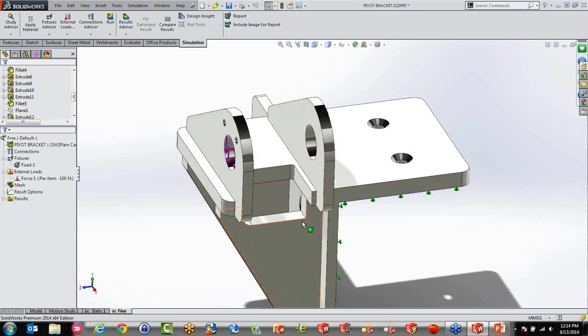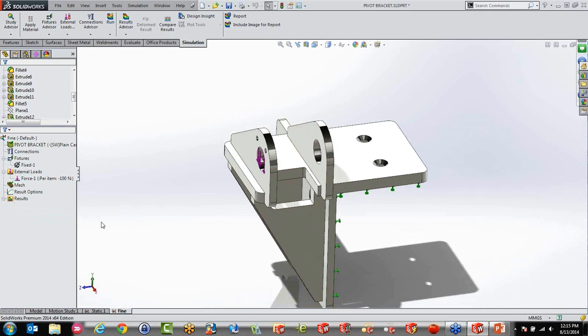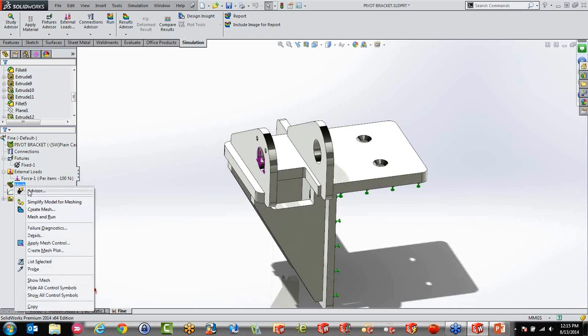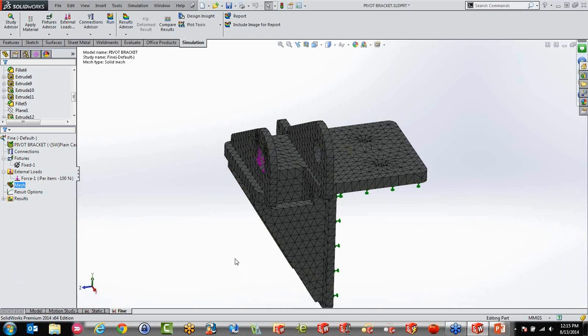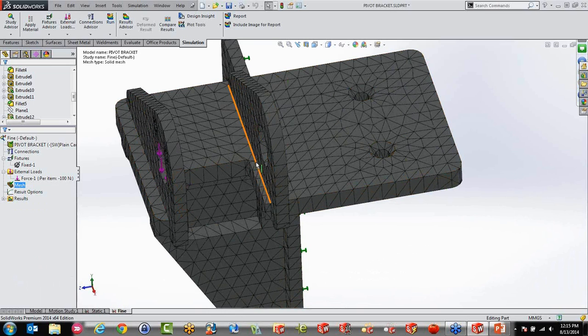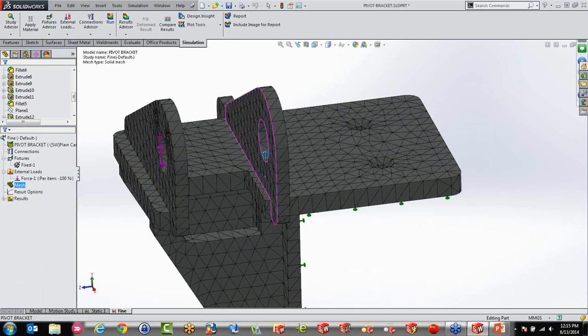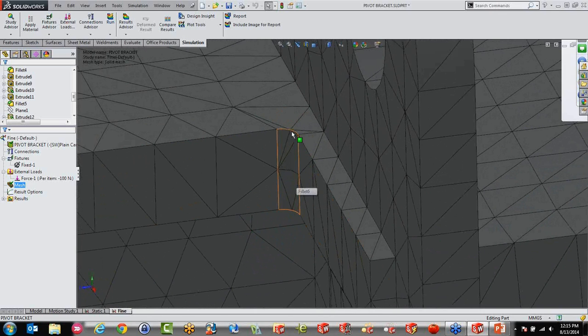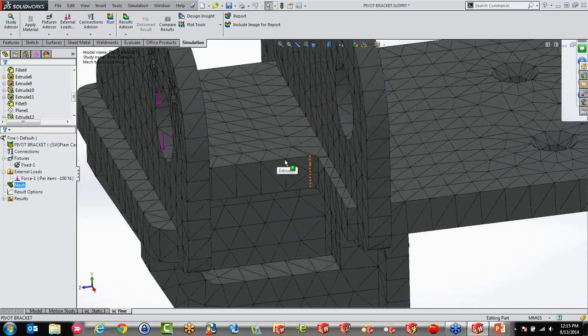So now I might go in and say, well, I realize that we got some results, but if we look at the mass in here, so I'm just going to right click here and say show the mass. This was what SolidWorks kind of defaults to. Now I maybe want to get a little bit finer result of what actually is happening in this area. So simulation is using these meshing parameters.